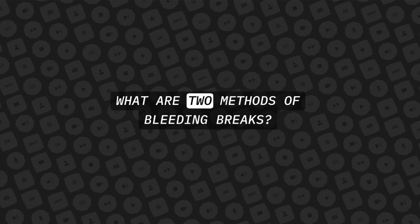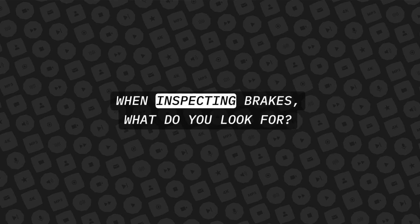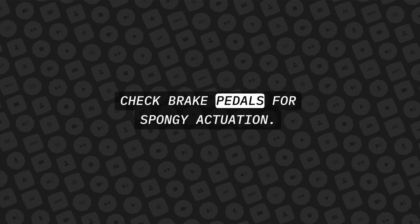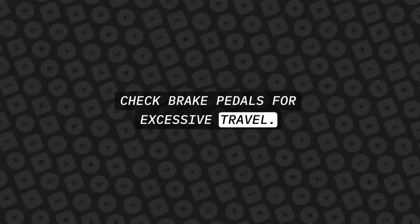The brakes need to be bled. What are two methods of bleeding brakes? The gravity method and the pressure method. When inspecting brakes, what do you look for? A. Check for leaks while the system is pressurized. B. Check flex hoses for swelling, cracking, or soft spots. C. Check brake pedals for spongy actuation. D. Check brake pedals for excessive travel.